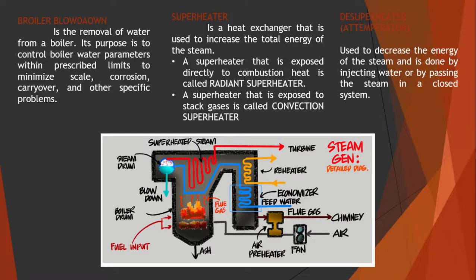The boiler blowdown is the removal of water from a boiler. Its purpose is to control boiler water parameters within prescribed limits to minimize the scale, corrosion, carryover, and other specific problems.